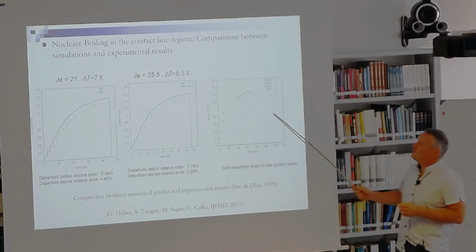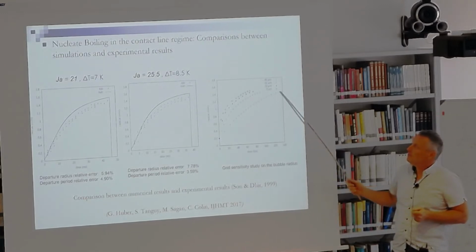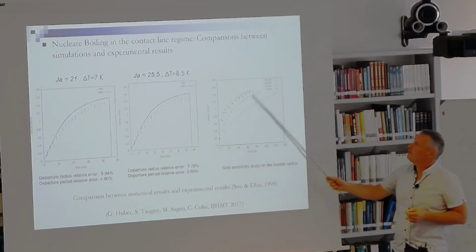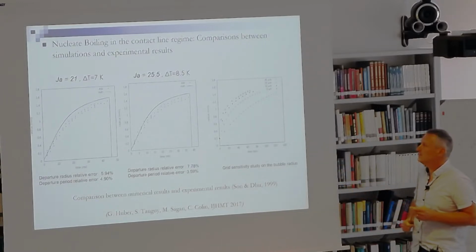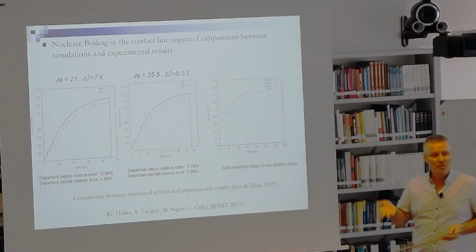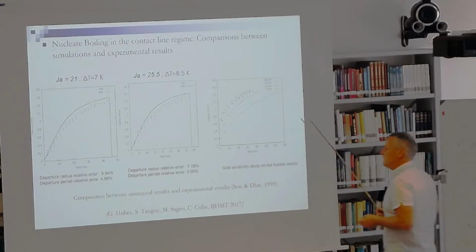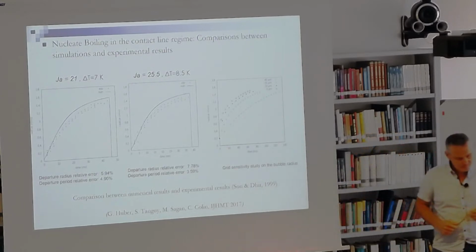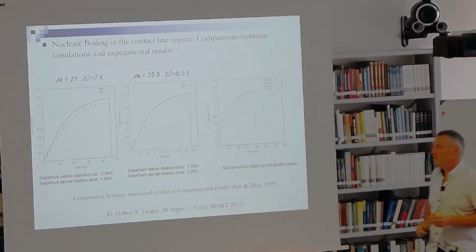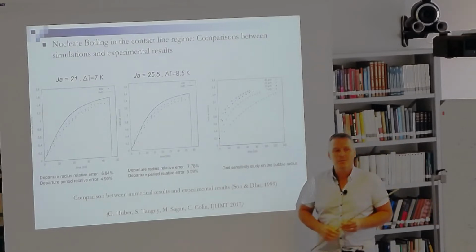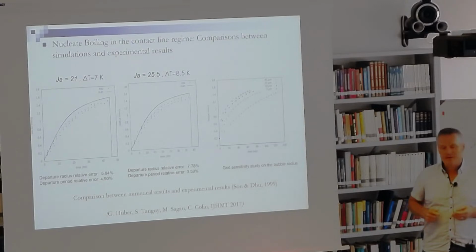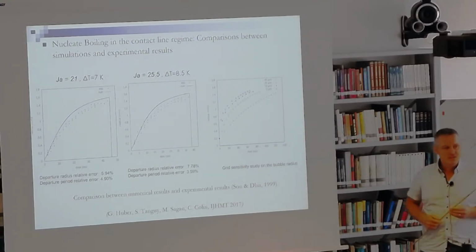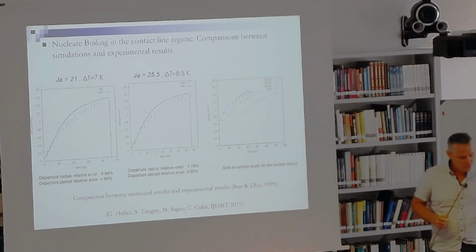And our simulations are well resolved. This is what we can observe here with several mesh sizes between 10 microns and 5 microns, which seem enough to have a well-resolved simulation that is grid independent. So, if we conclude about this, it seems no extra models have to be imposed at the contact line for this case, since the results seem good.